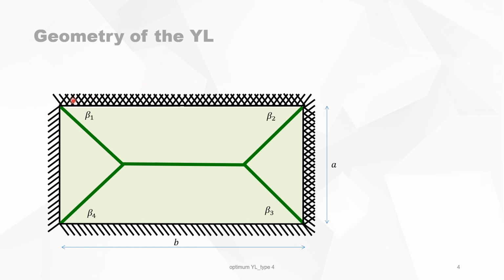Of course, when the slab is fixed, then we also have a yield line for the bending moment on top of the slab, and the same for this side. We assume that the maximum bending moment in the field is the same as the maximum bending moment at the top of the slab.